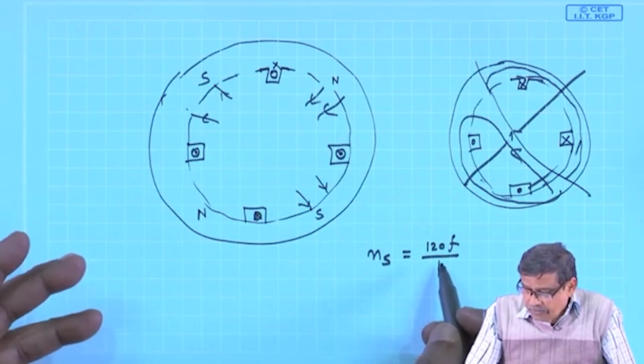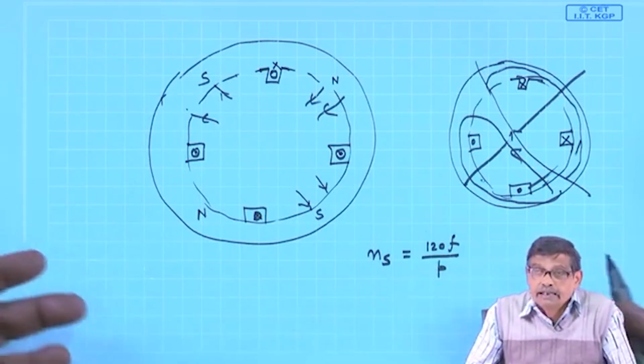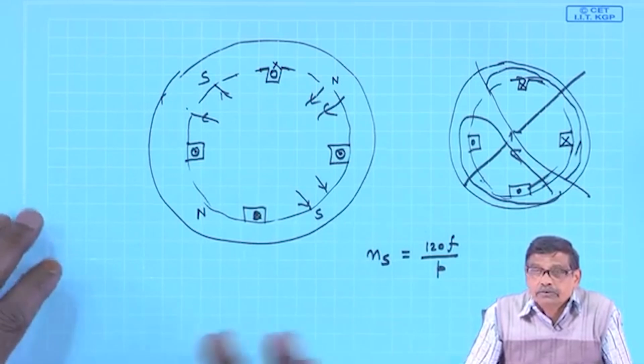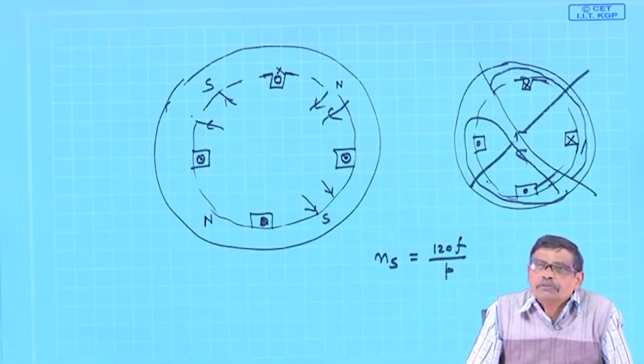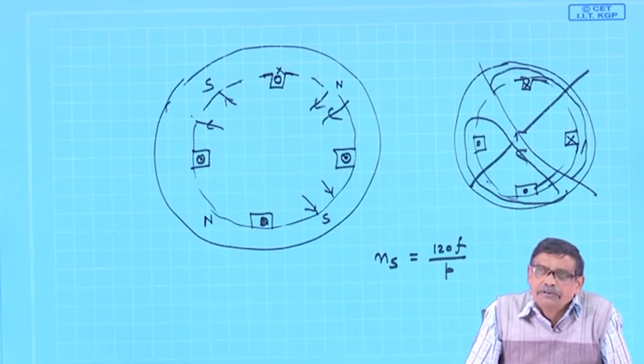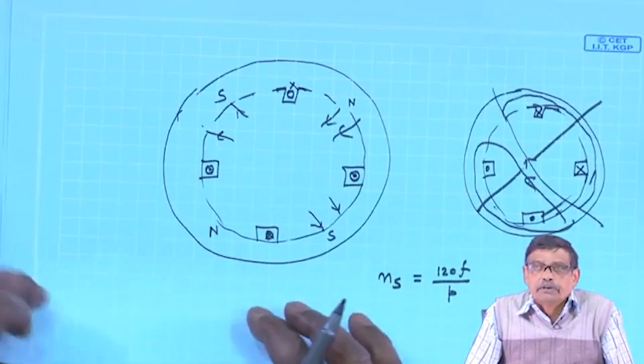So, people thought whether, with the same windings, P can be changed, hence Ns, and this cannot be done continuously. No continuous speed control is possible, only 2 discrete levels of speed you can have from the same induction motor. Anyway, we will continue our discussion from this point. Thank you.